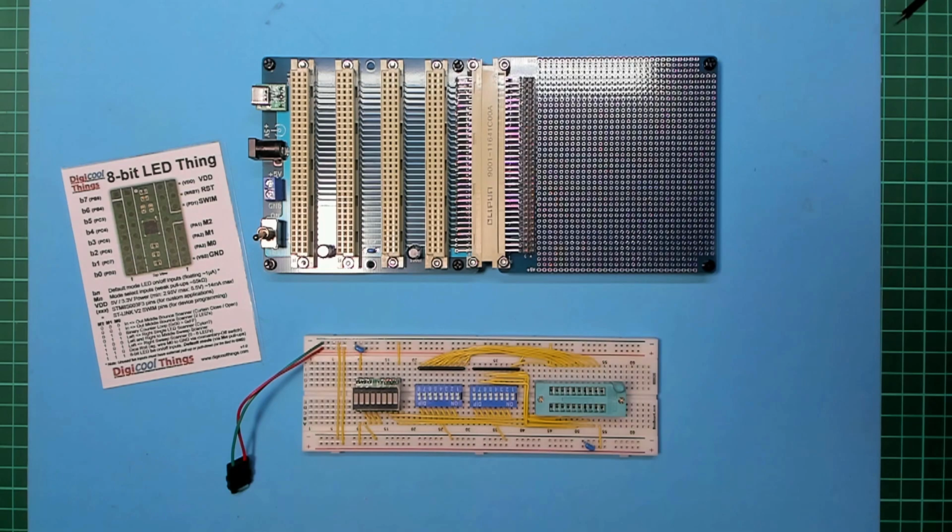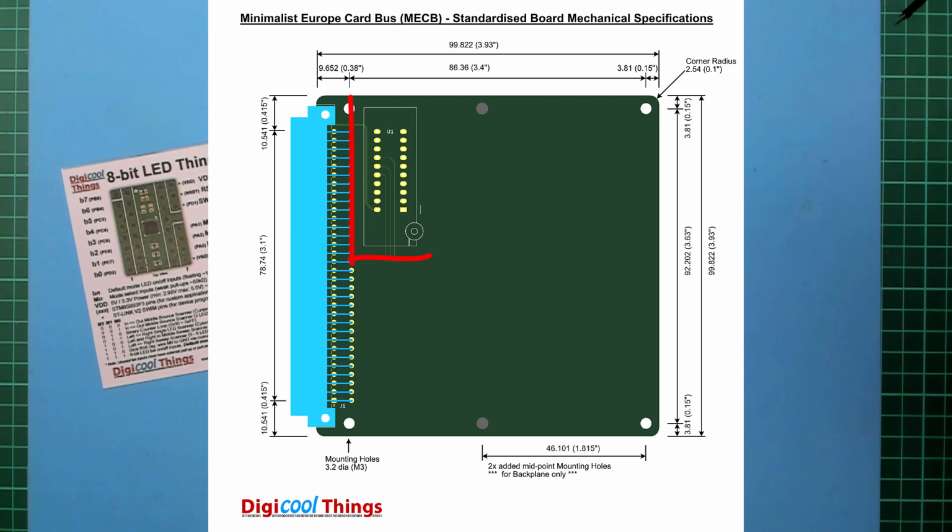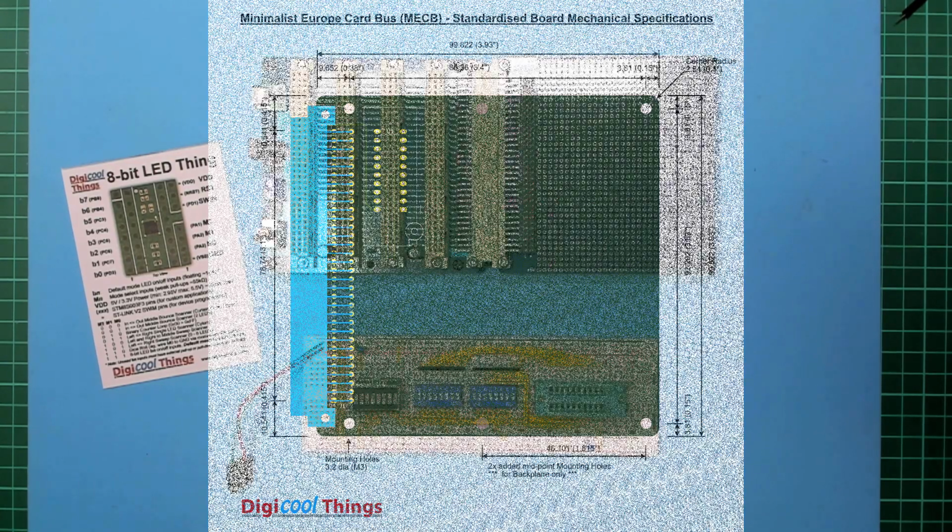By defining this initial ATF16V8 standard MECB Pin Allocation assignment, this enables it to be included in my MECB standard board design KiCAD template, simplifying the process of designing a new board. If sufficient PCB space is available, it's also worth ensuring that the PCB space allocated for the ATF16V8 can optionally support a 20-pin zero insertion force socket to provide for ease of address decoding swap-outs.